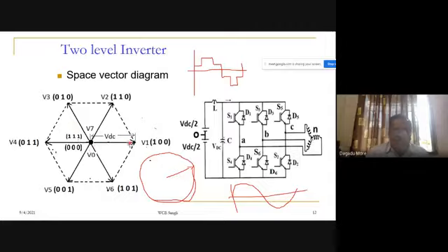If the space vector is rotating in six steps, it will remain 60 degrees at one pulse and jump to another. So it is not rotating smoothly; it jumps from one place to another instantaneously in steps of 60 degrees, and at that instant it remains in a steady position. Then our output voltage waveform will be a six-step output voltage waveform, which contains harmonics.